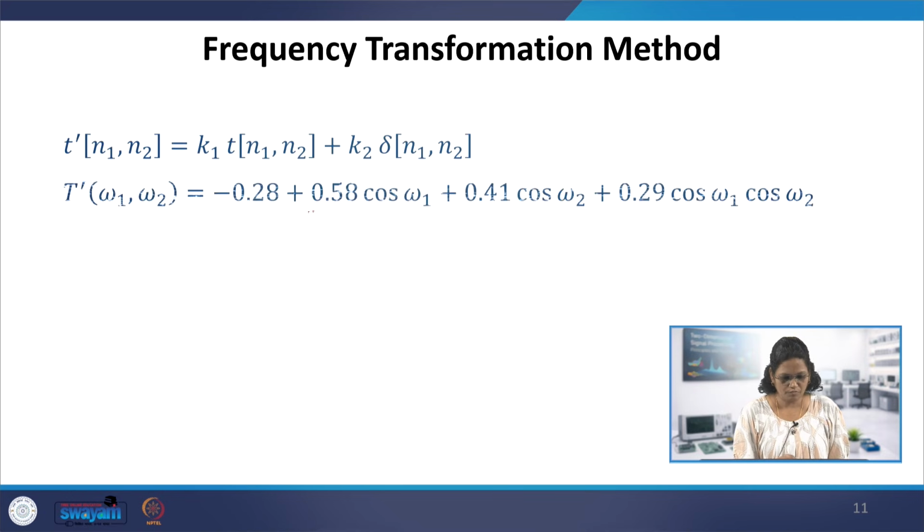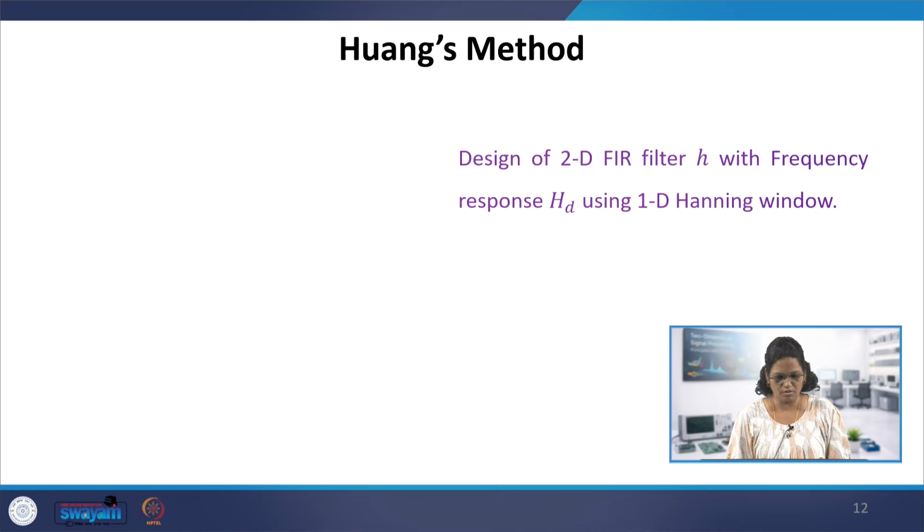With this equation, the coefficients A, B, C, D obtained for T dash are different now. So the transformation function is further refined to have a better response. These are not the 1 by 2 or 1 by 4 coefficients we had in the previous example. This design procedure gives a better frequency transformation function to meet the specification. So this is one procedure. This example we will see as code in the laboratory demos. Further details of obtaining T dash and the constant coefficients of T in the previous example, and their implementation, we will see in the laboratory demonstrations.